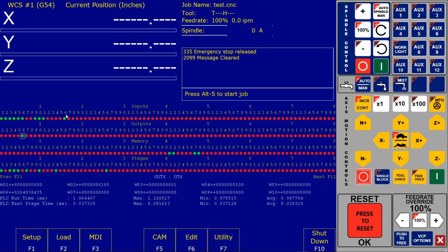All right. But let's say I'm going to flip it open, and that input is now normally open rather than normally closed. So I'm going to go in here and invert that state. All right. You see that turned green? There's a white line that's telling me that the logic is now normally inverted, or I'm sorry, normally open, which means that it has been inverted.